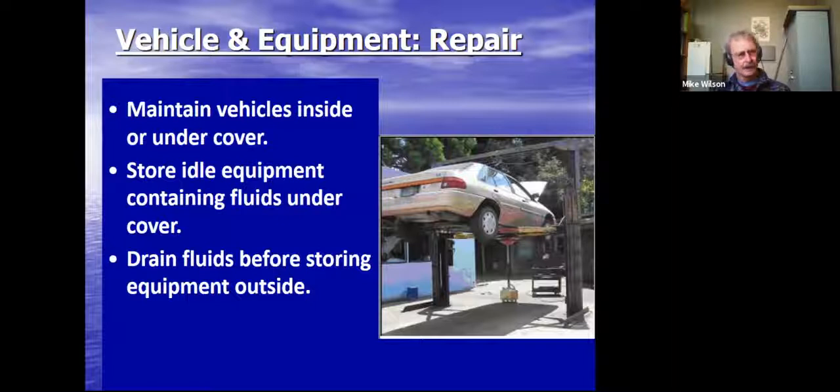You want to maintain vehicles inside or under cover in terms of repairs. But if you're going to store idle equipment, try to keep that under cover. And if you can, drain the fluids before storing that equipment outside. You don't want a leaky transmission slowly leaking into the ground. In time, it will pollute the ground.